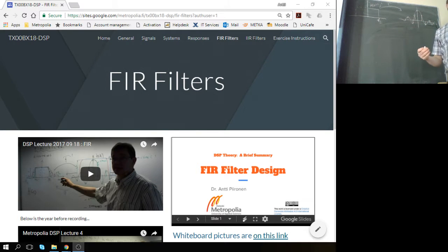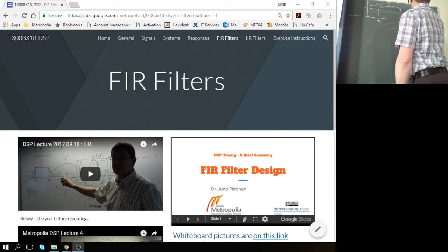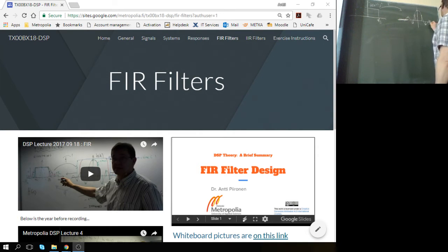And how to make it a finite impulse response? Well, you cut it there, for example. So set the value to 0 after those points, meaning mathematically that you are multiplying this sinc function with a box. So there's a w of n, and there's also that sinc type function.